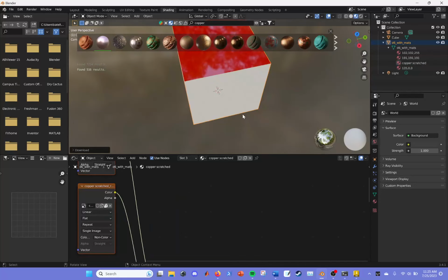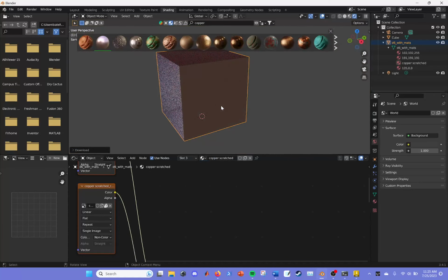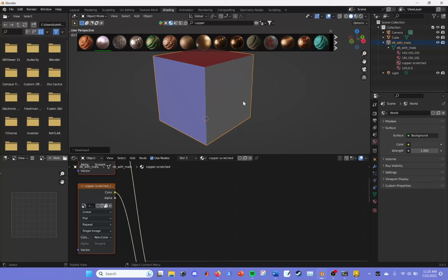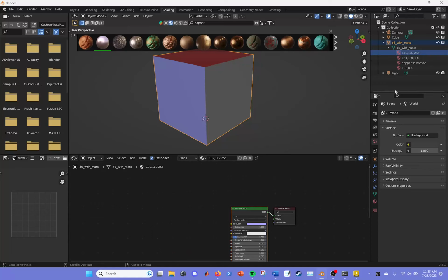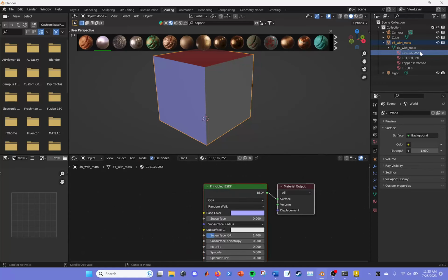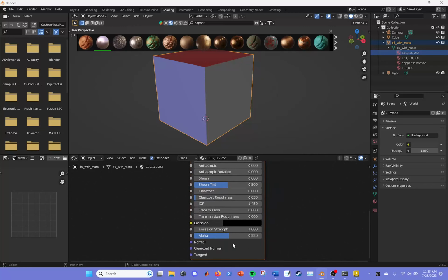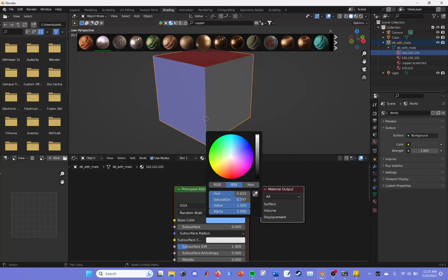I can go into Blender Kit and choose a new texture, and you'll see that even the name in the Scene Collection browser will change with that new material. If I want to edit a different material within the same object, maybe the blue glass, it's important that you do that in the Scene Collection browser. We can see that the one I just selected is the glass because the alpha value is not quite 1, or opaque. If I change the base color when we go into render mode, the appearance of the material will change.